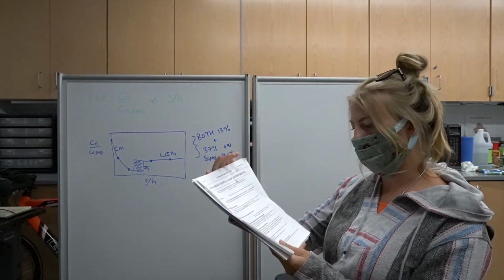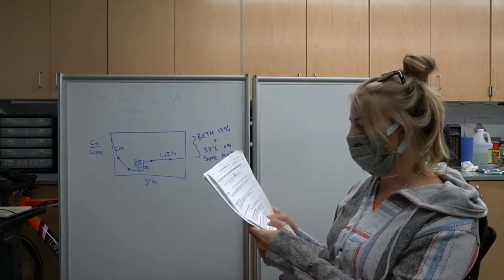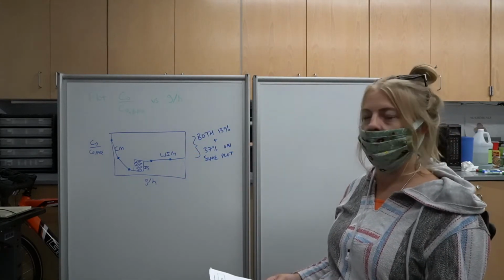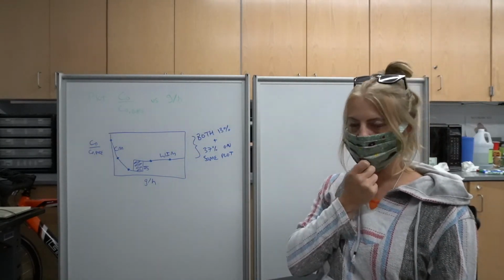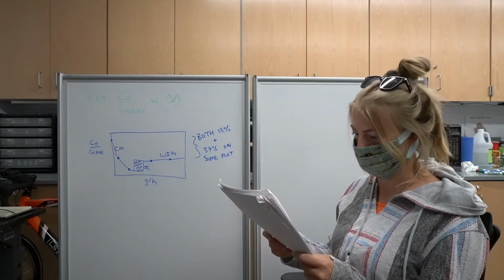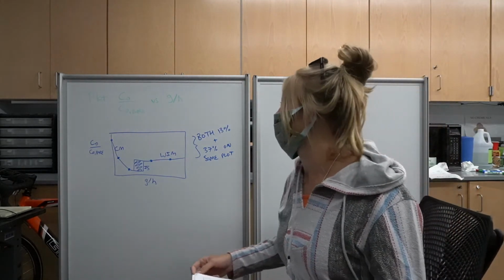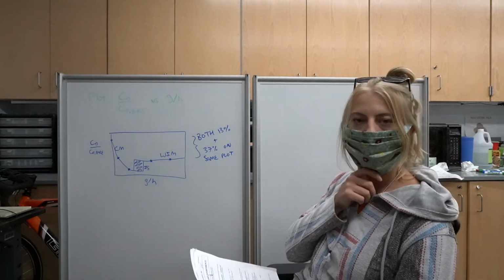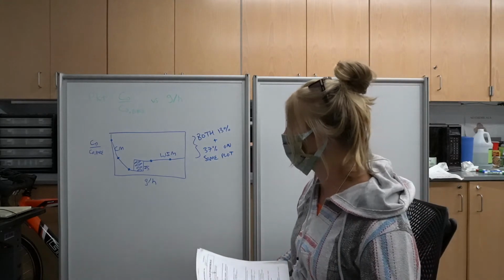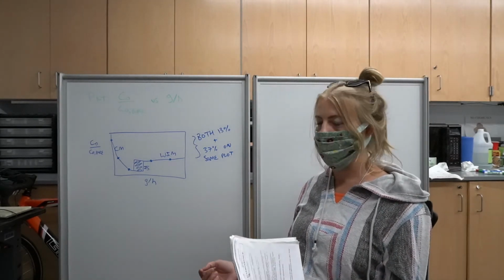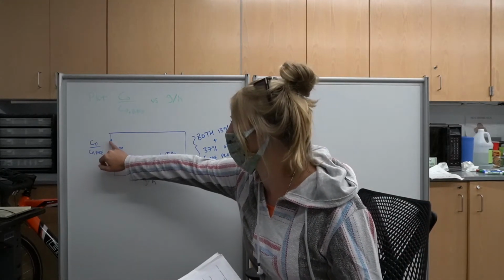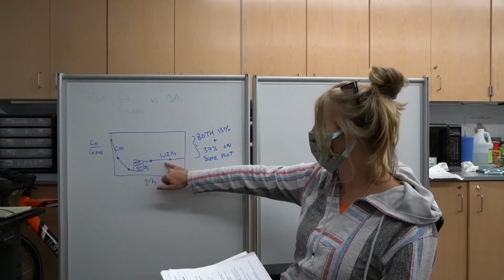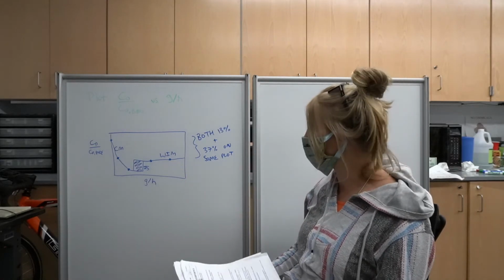Okay, so the last point of 3.2 that you're going to be doing is discussing CD over CD bare versus G/H for your two plates, 13% and 37%. So this is the plot that looks like this. So a few things that you want to take note of when you do this plot. Firstly, we're going to be labeling our different modes. So cavity mode is going to lead to this big drag reduction. And then wake impingement mode is at the higher G/H's.